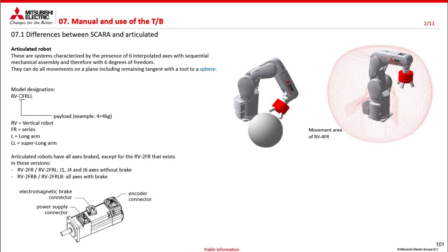In this image, you see how a J4 series motor is made, which are the motors used by Mitsubishi. We start from the motor element, in the central part there is the electromagnetic brake part, which is simply a parking brake that is engaged when the torque of the axis is removed, and in the final part we see the encoder part.